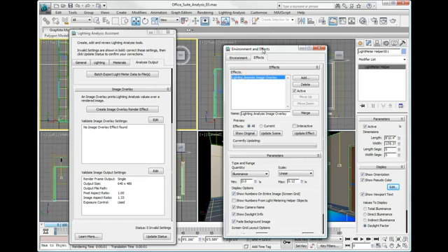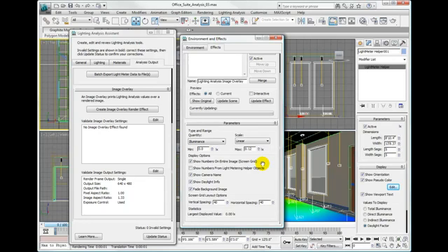Down in the Parameters area here, we have several parameters. Under the Type and Range, we have the quantity, meaning whether it's illuminance or luminance, and the scale, whether it's linear or logarithmic. Well, we're going to measure the luminance. However, notice that we do not have the ability to measure the daylight factor as an overlay. This daylight factor is just available in the light meter within the viewport as a measurement.